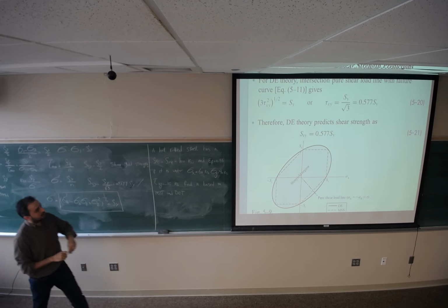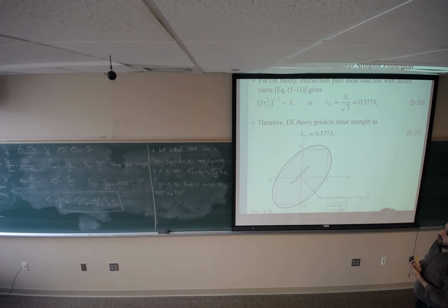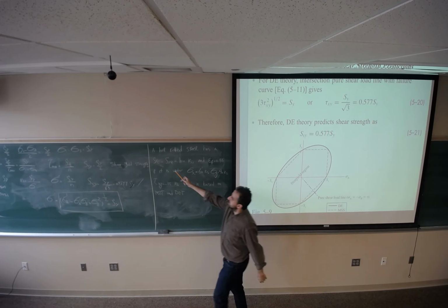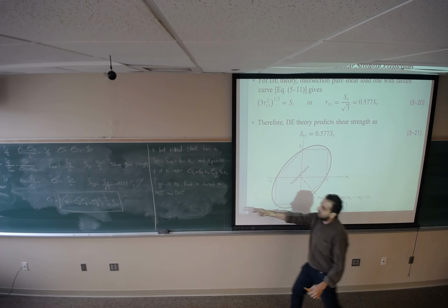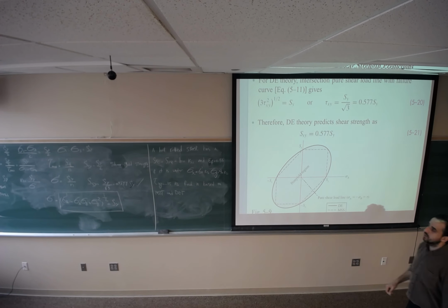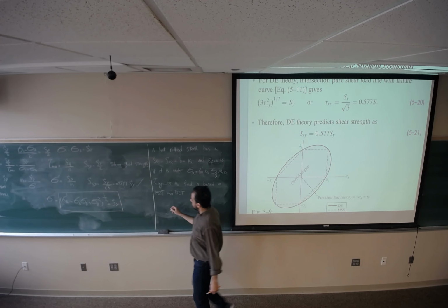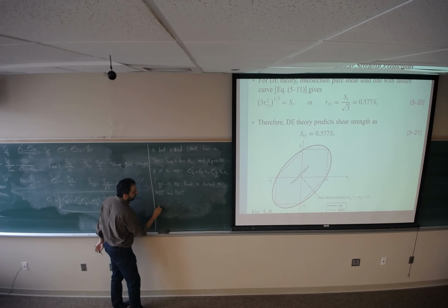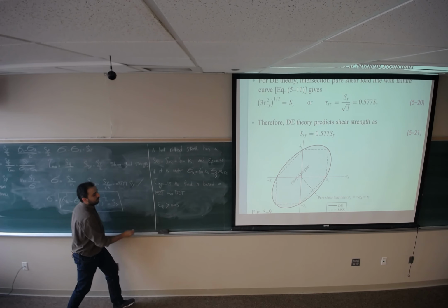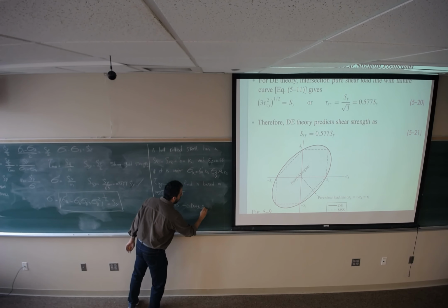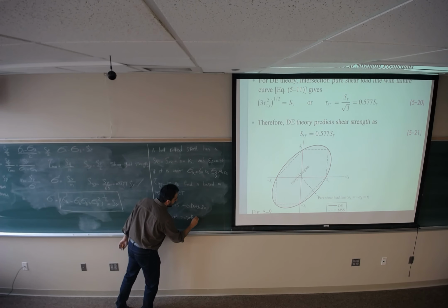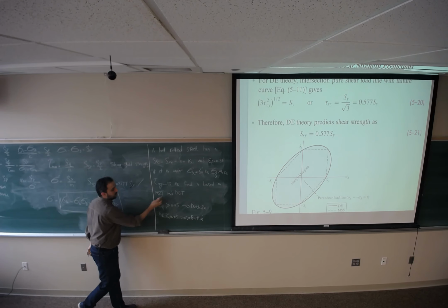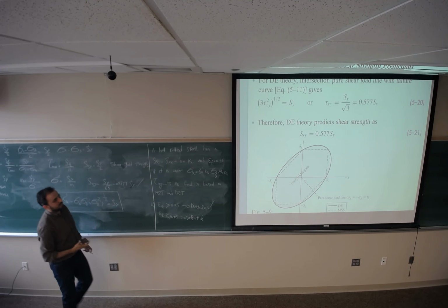So we have a mechanical component made of steel with these mechanical properties. As you see, for compression and tensile, they have the same strength, so we can use these two theories. Otherwise, we cannot use these two; we have to use the Ductile Mohr. Why are we given this? Because we should first check if we have a ductile or brittle material. If the strain at the fracture point is greater than 0.05, we have ductile. If it's less than 0.05, we have brittle, and you cannot use these two. Since it's 0.55, we can be sure it's a ductile material.